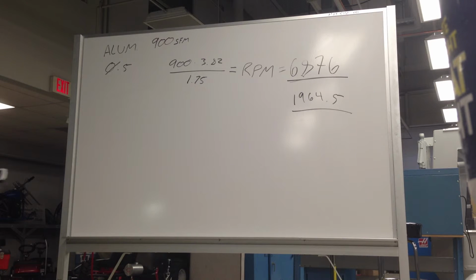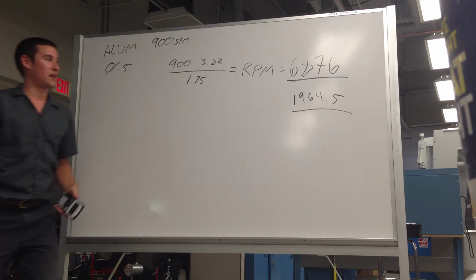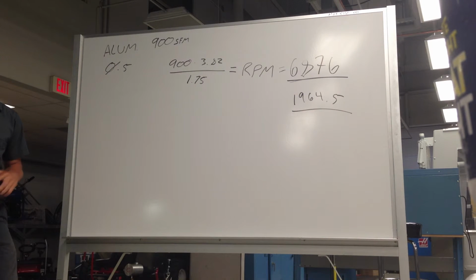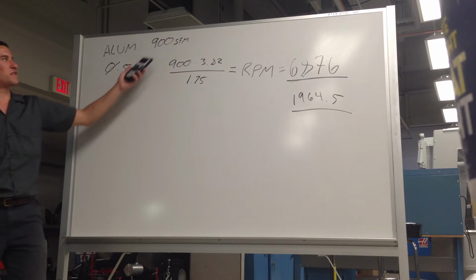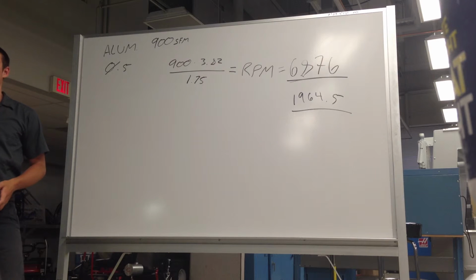You're right. If you're back on the Bridgeport and that thing only spins at 4,000 RPM, or not even that, probably it spins at 3 something, and you want to get a high surface speed per minute, you should probably use a bigger tool, right? That'd be a quick and dirty way to do it.